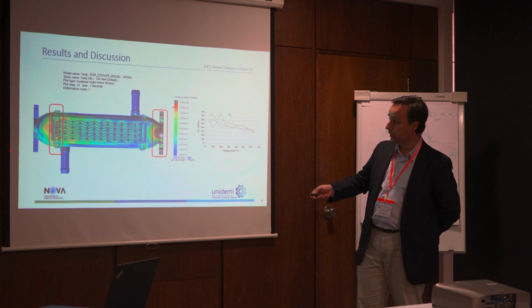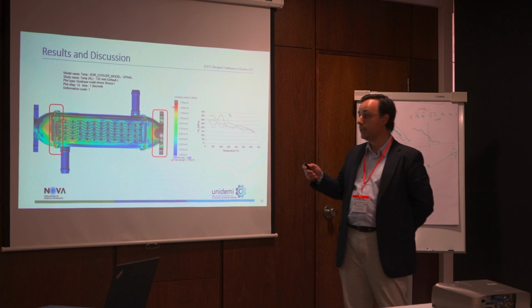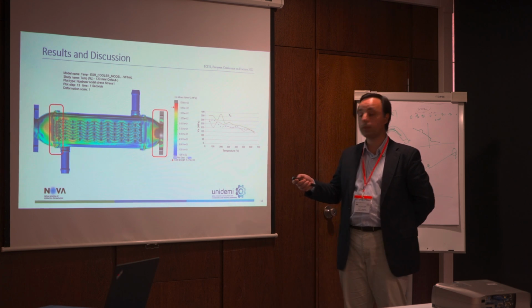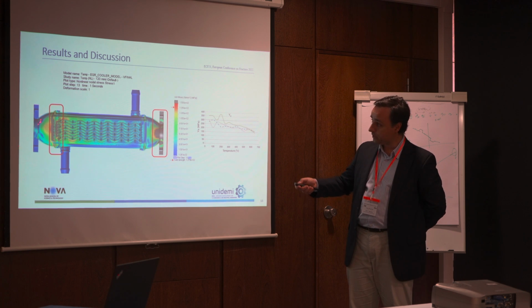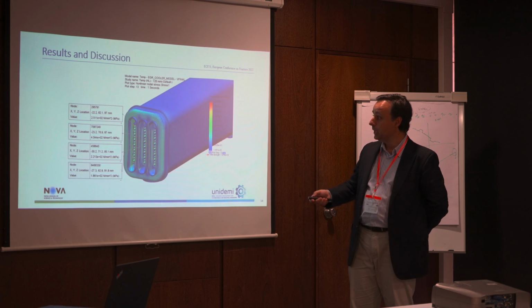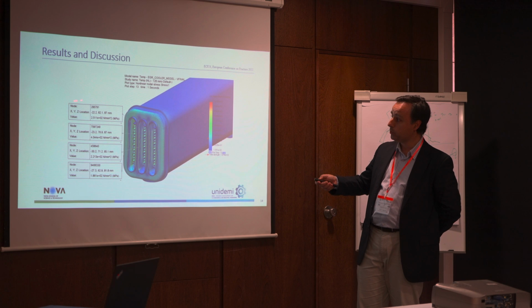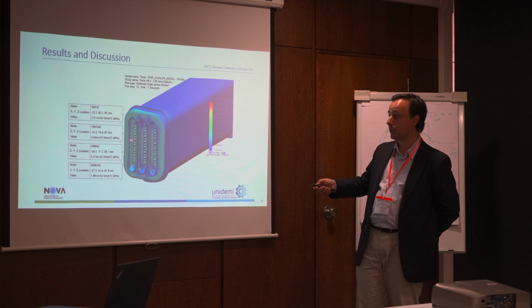On the left, we can see the thermomechanical stresses that are induced and are higher than 150, and that exist on the baffle, as you can see here, and also in the entrance of the fins, as you can see here. So this is important. Looking in more detail, we can see that those stresses occur in the baffle and in the fin at the entrance of the fin, and range from 250 megapascal, and could attain 400 megapascal, like in the fins, in the curvature, in the stress concentration parts of the fins.